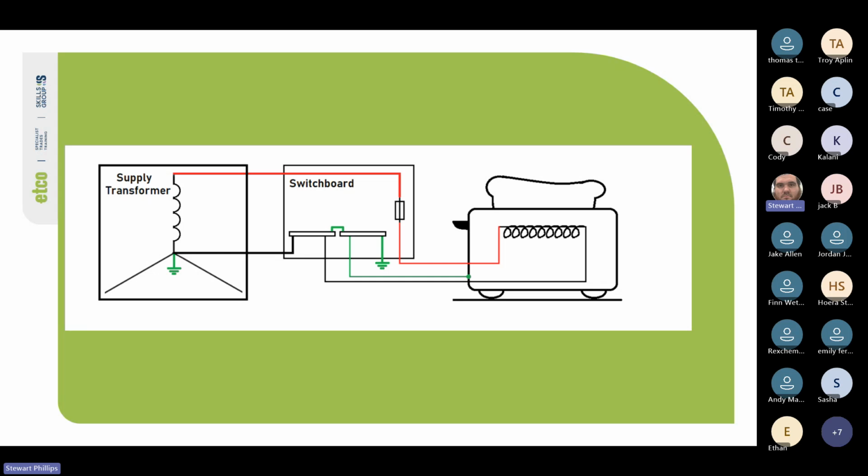So it seems like a huge loop, but most of the time in a residential setting you'll come back with maybe 1.03 ohms. I believe on a 16 amp 2.5 circuit, you can have up to 1.82. Don't quote me on that, I don't have the table in front of me, but it's something like that. Usually you don't get that. At a switchboard, the worst I've seen is 0.05. That was a crazy high reading, but we had the right switchgear for it.